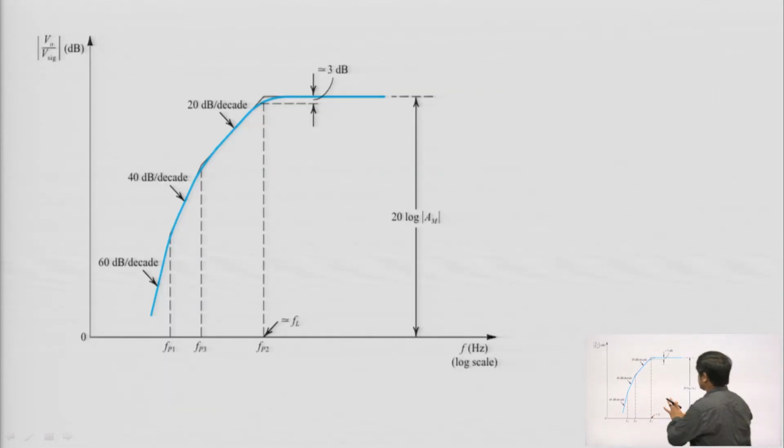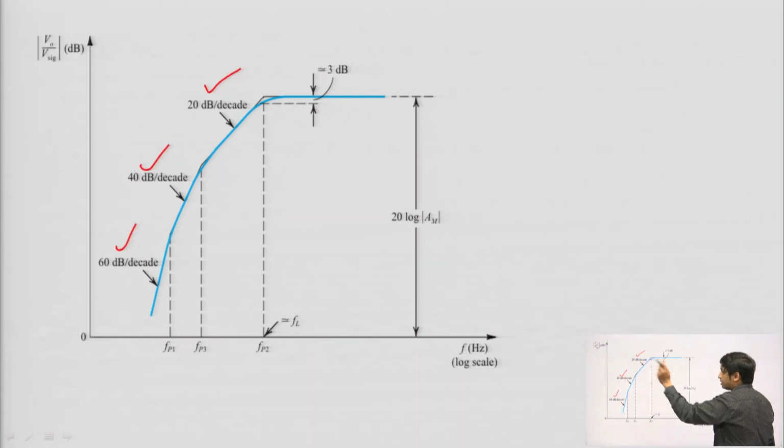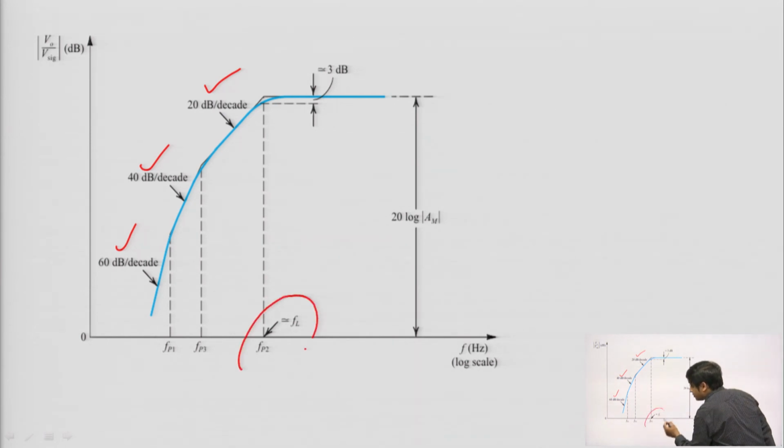Now, after that, this is the low frequency response. In low frequency response, the gain is reduced at low frequencies. Since there are 3 corner frequencies, firstly there is a slope of 20 dB per decade, then 40, then 60. The highest frequency is the second corner frequency, that is Fp2, because there is a transconductance term in the numerator and the transconductance of the Cs amplifier is higher.